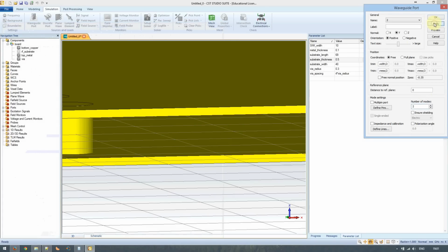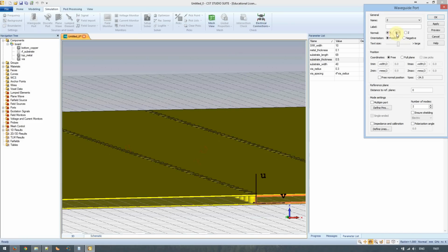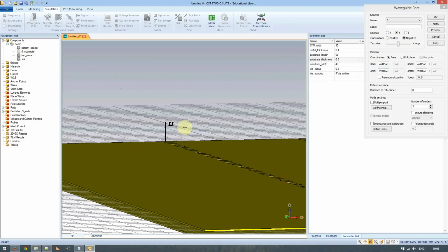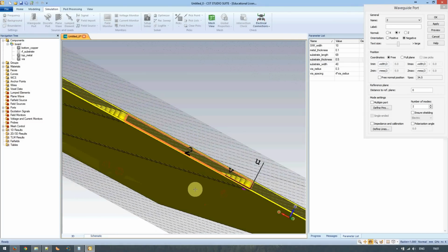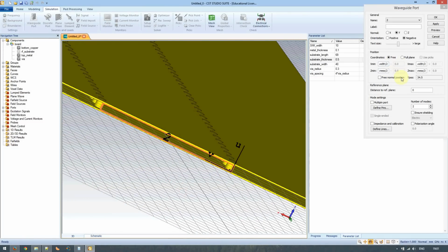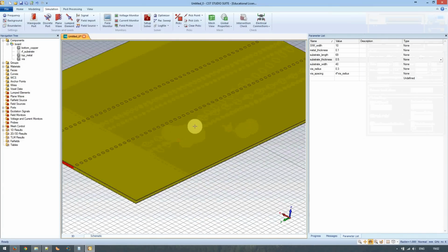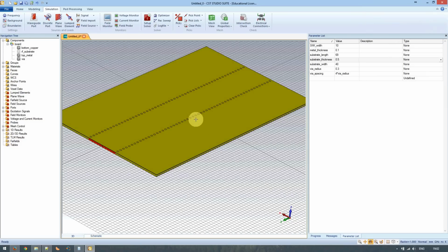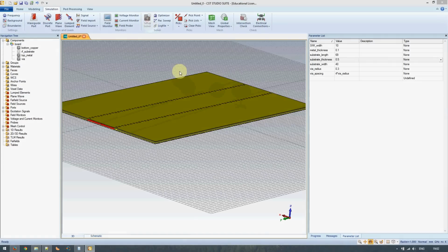Okay, click apply. Then it will go automatically to port 2. And for some reason, CST is a little bit buggy, in that even though it had Y selected, it was pointing in the Z direction. Anyway, never mind, negative. So you'll see that the negative port has appeared on the other side. If I flip the model around, it already has the right sizing because it's kept it from what we did the first time. It already has 2 modes. So we just click OK. Right, so I think that is it as far as our model goes. Now, what I'm going to do first is here, click Setup Solver.